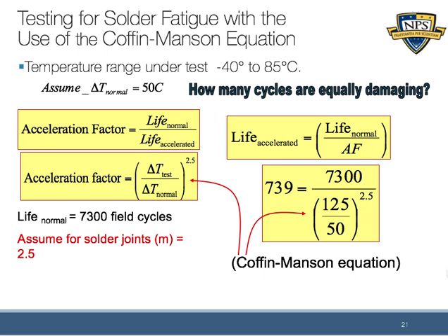And also, depending on what type of component you have, some components are only rated up to a certain temperature. So you have to be careful not to put the temperature too high or too low, because it could actually destroy the component outright. And then you would force other failures that you're not looking for. So that's important to understand.